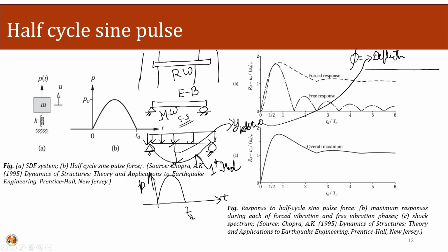The numerator part is the deflection equation, and the denominator part is the deflection equation evaluated at the center. This will give the signature of the mode shape, and the signature of the chosen degree of freedom.